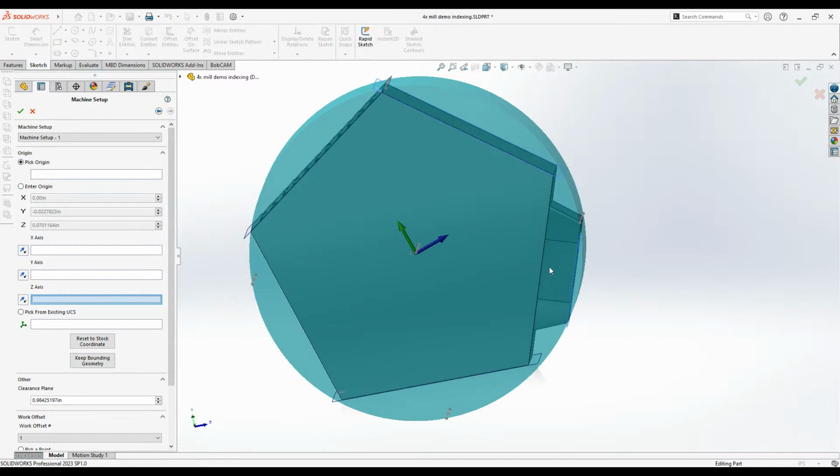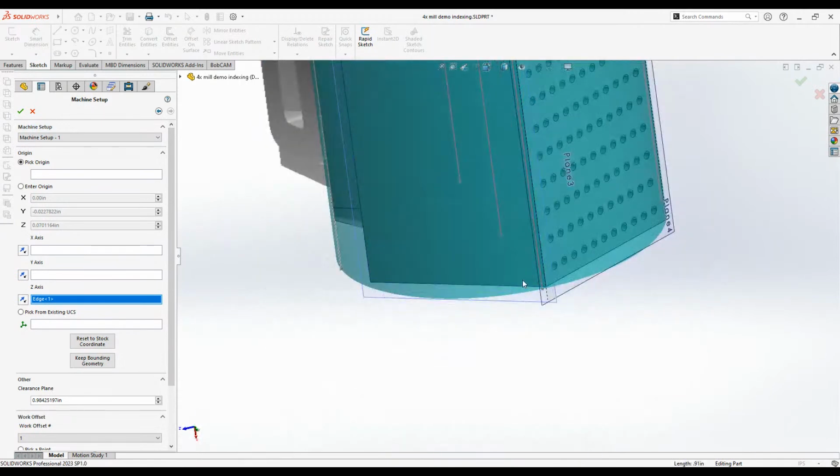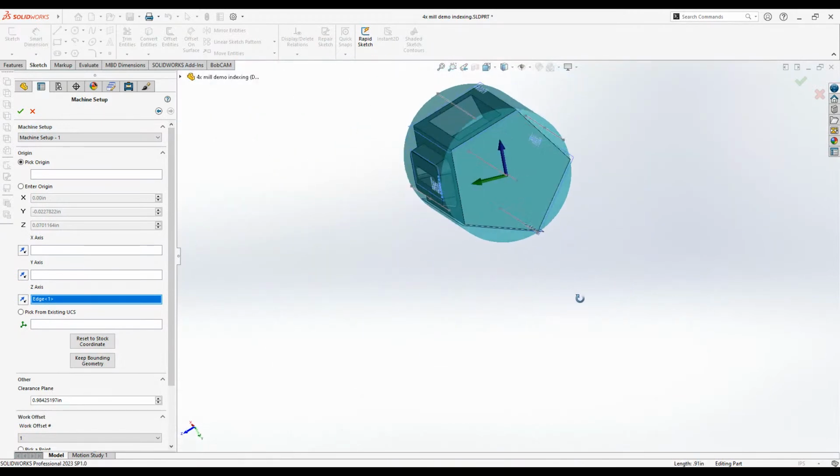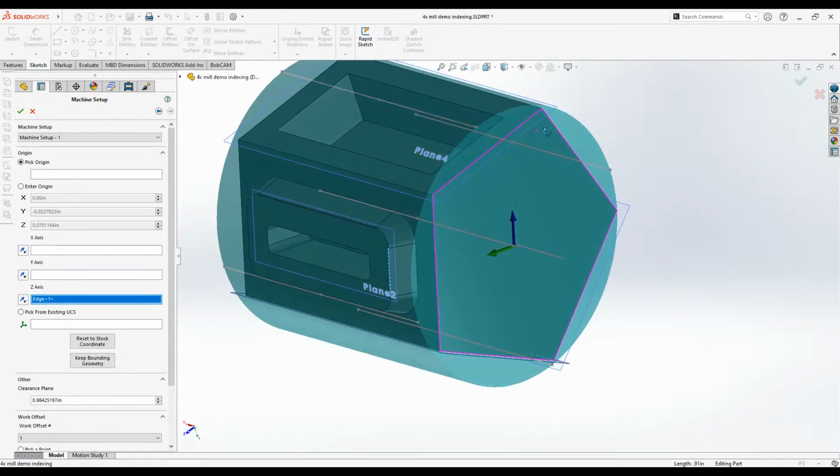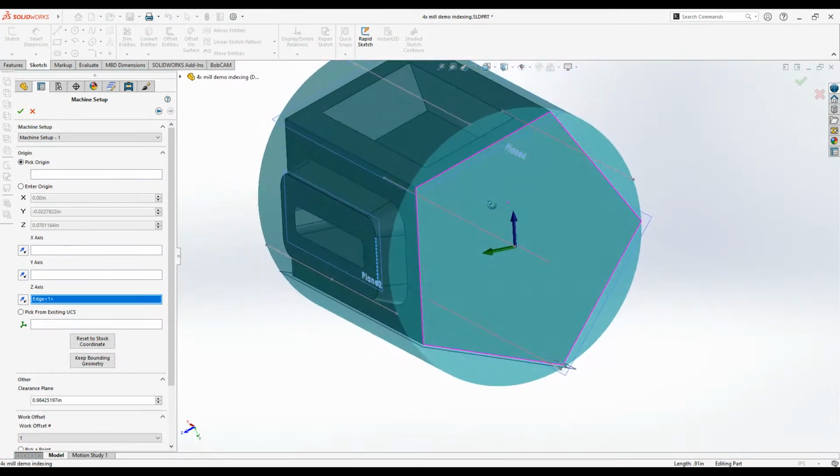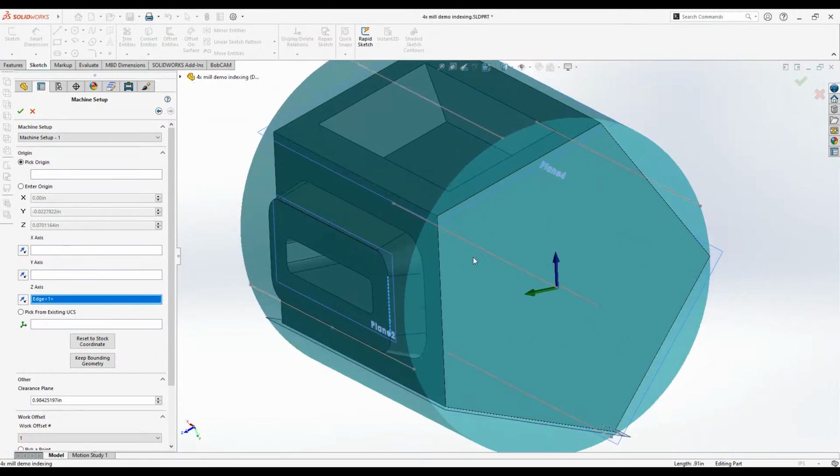So I'd highlight z-axis, make it parallel to the line of the, yeah, so it'd be something like this here. So the z-axis would be pointed down, and then we can use the side of the tool to mill out that area with our z-axis pointed parallel to that direction.